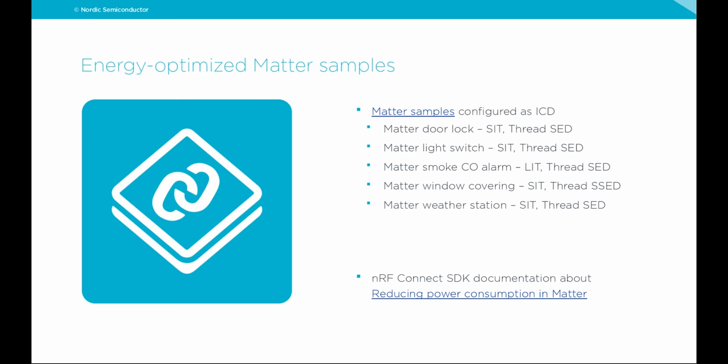First of all, we deliver our nRF Connect SDK that includes various Matter samples. Several of them are energy optimized and they present different variants of ICDs and Thread sleepy devices configuration. So let's open it.